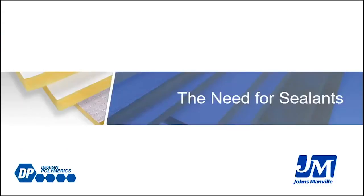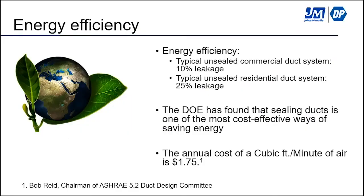The need for sealants. The most important is energy efficiency, and energy efficiency translates into cost savings, into money. A typical commercial system, even with a contractor's tightly fitting duct, is typically 10%, usually greater, of unsealed duct. And on the residential side, it's closer to 25%, and quite often much more than that.